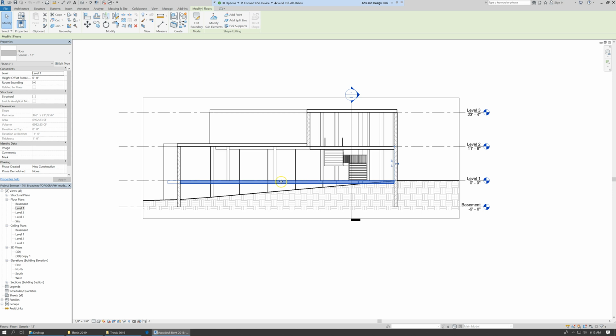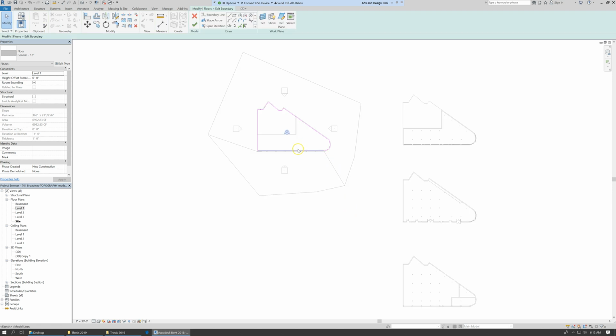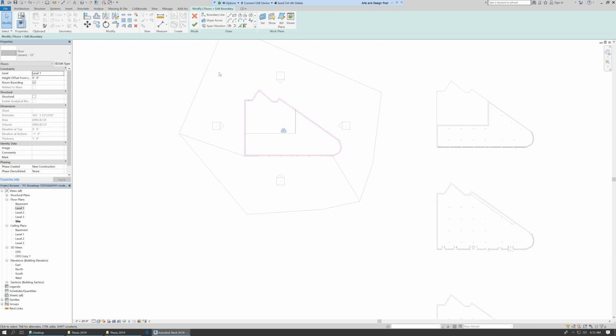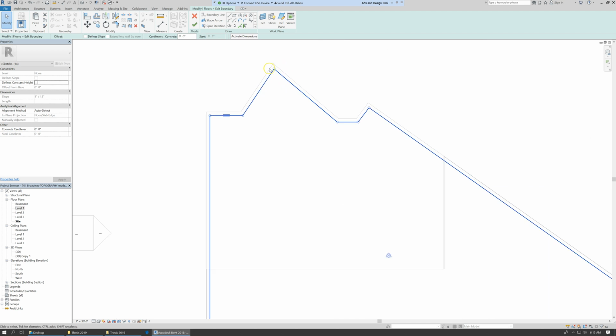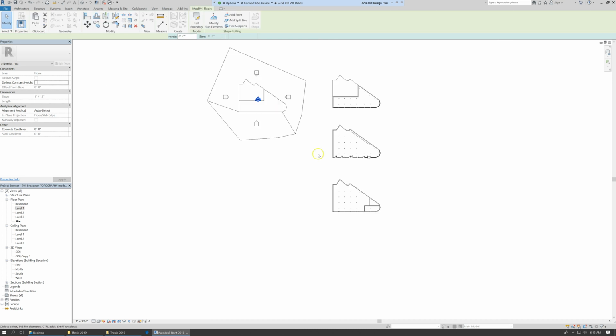Rebecca's already drawn this floor, I could edit the boundary of the floor. I'm going to go to the site plan. Okay, puts me in sketch edit mode, so I have the outline of the floor. I'm going to select these lines, copy them to the clipboard. They actually need to be offset so that they're to the outside of, and then quit out of this.